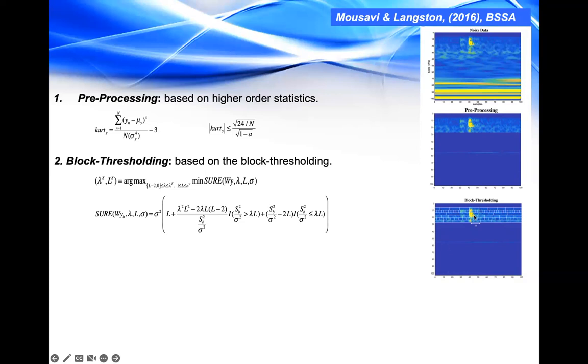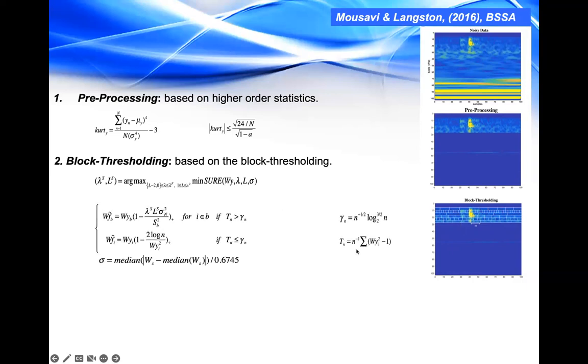Then all coefficients inside each of these blocks are attenuated simultaneously using this characteristic function. To use this function, we need an estimate of the noise level, which is obtained from a pre-signal window. So here we need a rough estimation of the arrival time in this method.